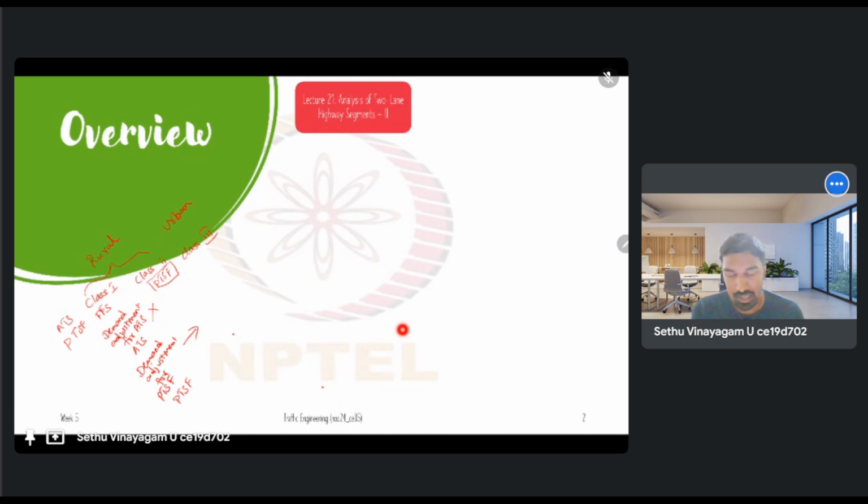When it comes to class 3, as I said, this is in the urban area. Here the performance measure is different from class 1 and class 2. The measure is the percentage of the free flow speed. Instead of using ATS or PTSF, we go for the percentage of the free flow speed that exists in the highway. So speed is the criterion for the LOS in class 3.